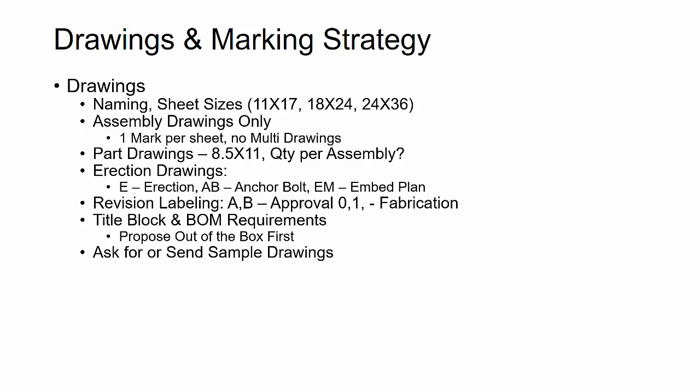Then the last really important thing here on drawings is that I almost always ask for sample drawings at the beginning of the job. If the fabricator doesn't have this shown in their detailing standards, I always ask, hey, can you just send me some beams, columns, and assemblies that are similar to this type of job, and send that as examples for us to start with? That gives us a good idea of what the fabricator needs, and what's going to be automatic from the detailing system versus something that we have to do manually.